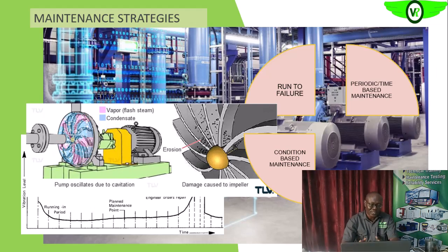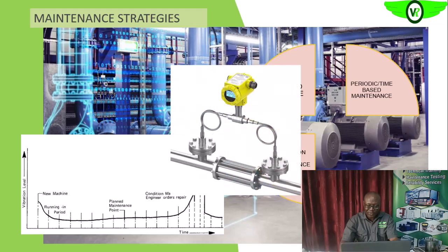So all of these parameters will help us to look at some of these conditions of that particular equipment. So across a strainer, which is on the suction of your pump, how do we monitor the condition of the strainer? We look at the differential pressure, delta P, between the inlet to the strainer and the outlet from the strainer, or discharge from the strainer. So as delta P is increasing, that will give us an indication that the filter is getting clogged.